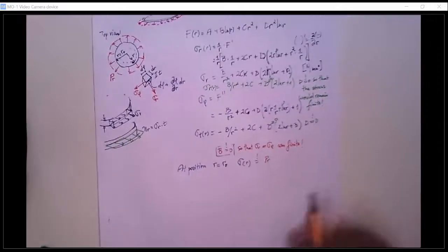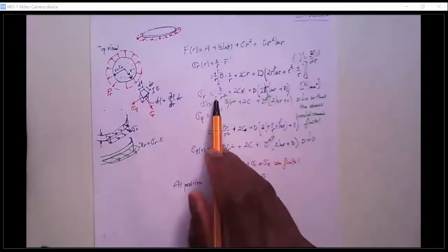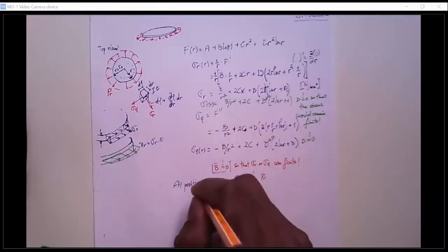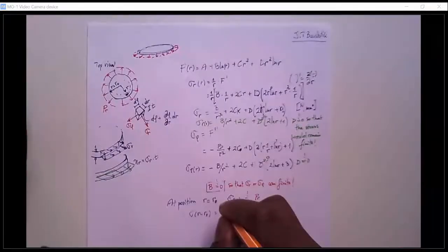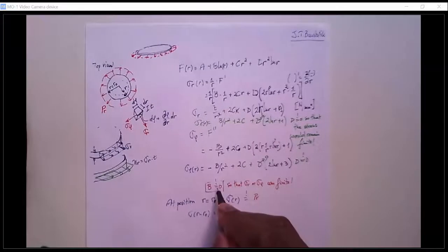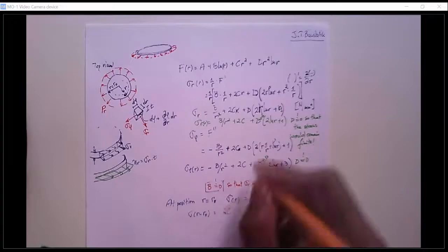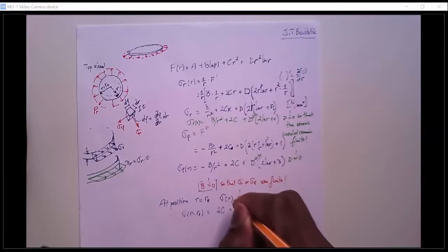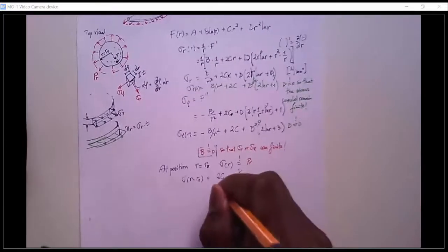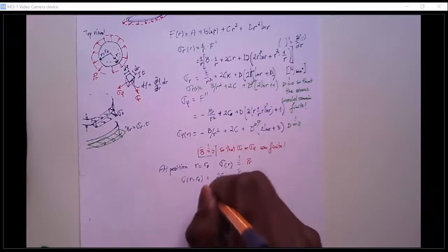Okay. How can we use this boundary condition? We have the equation. What is our equation? Sigma r at r equals the outer radius is, you can read it here, b divided by r squared, but b is 0, so we can just leave it out, is equal to 2c. Then the g part is also 0, we said it already, so 2c needs to be equal to PR, and then we can figure out that c is PR divided by 2.